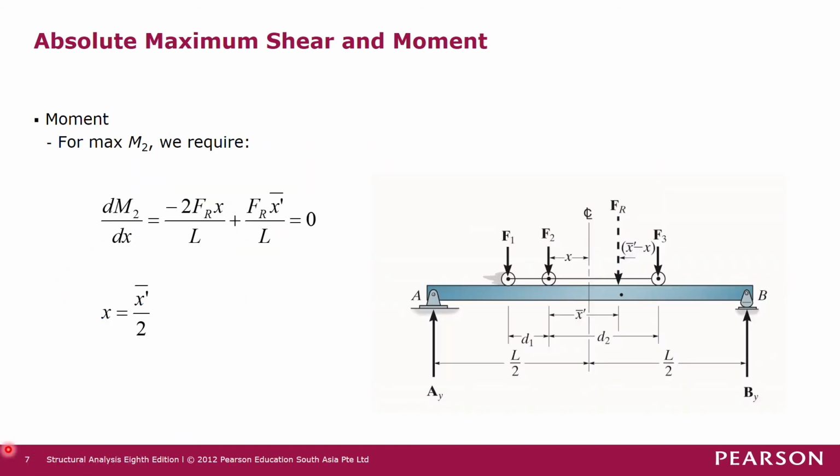Normally we start with the midpoint of the beam, where one point force put here will create maximum moment at the center line. So you draw the influence line for this beam at this point, and then determine the maximum moment due to this system of forces.